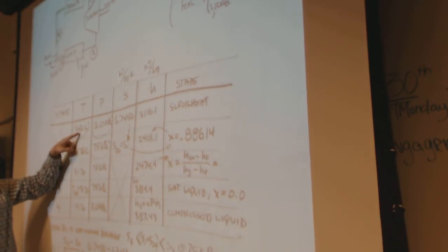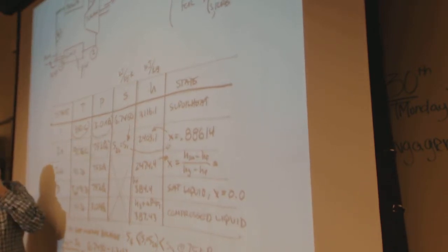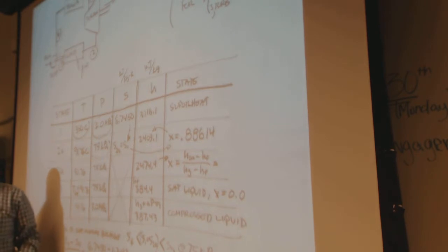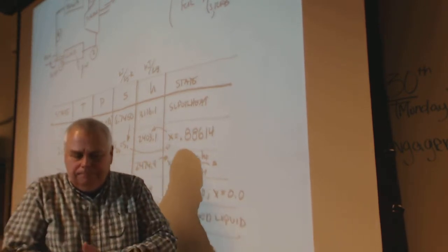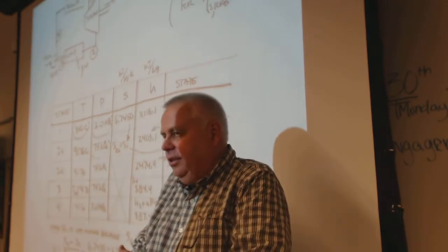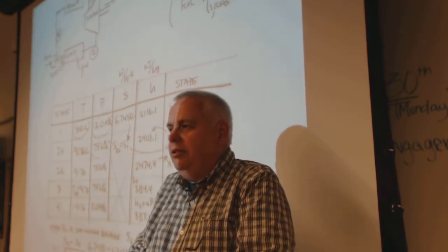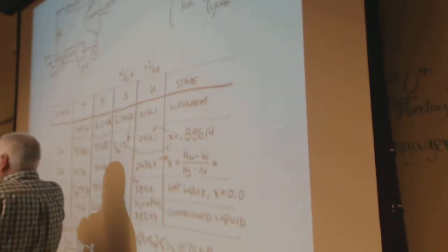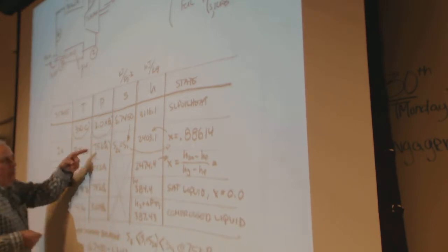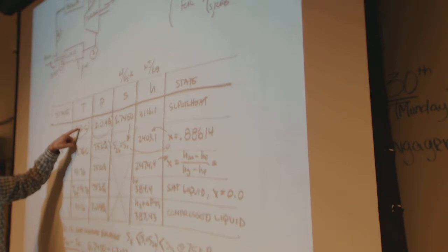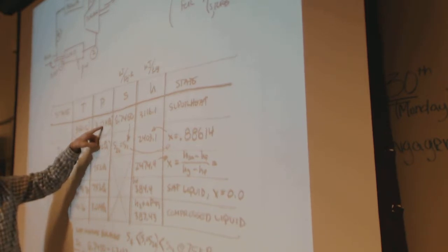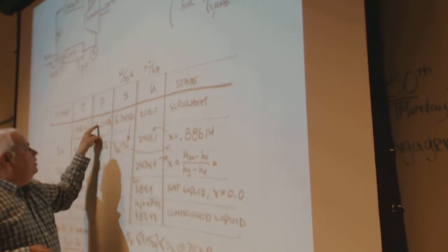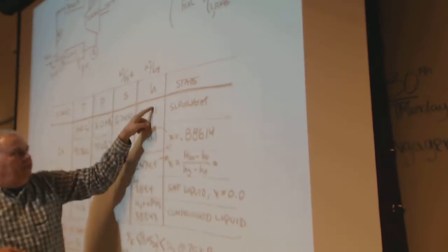Anyway, what we know is they told us it's 350 degrees C at 3 megapascals, and the pressure on the condensation side is 75 kilopascals, which is a vacuum. These are absolute pressures, so it's like suction. If you open the valve, it's sucking in because it's less than 100. Based on this and this, we can find this out of the tables. If you look for this, you'll find it's in the superheat table. When you find it, this data should show up.